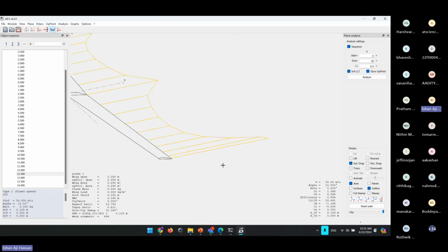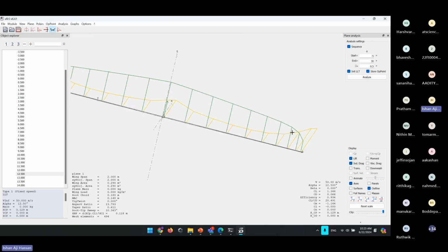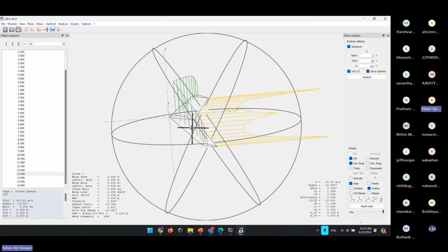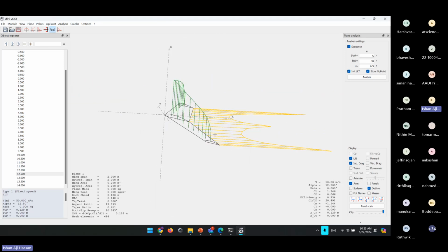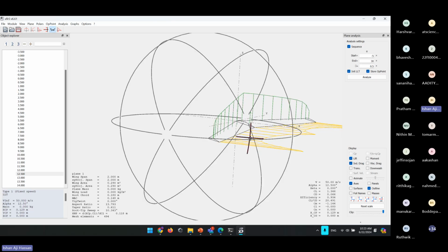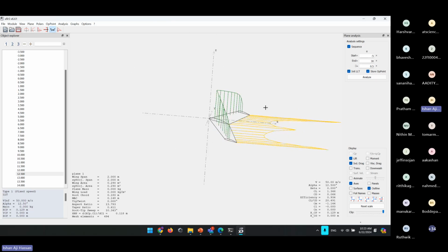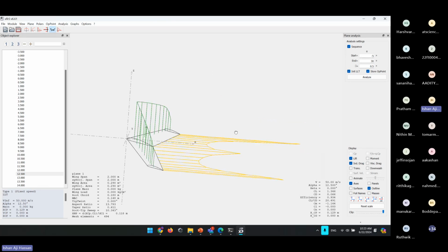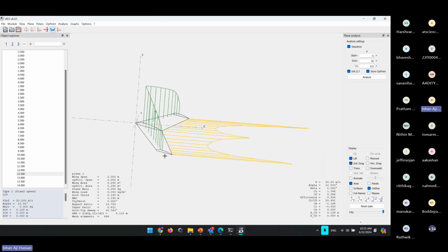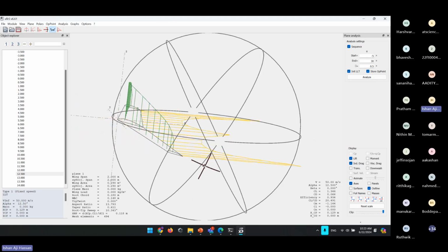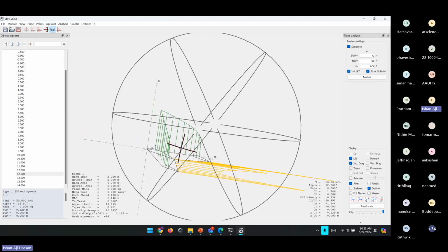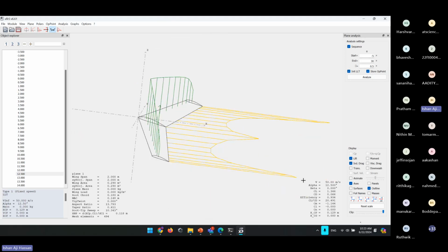And reducing the efficiency means that the lift component is basically angled backwards. So what happens is that this same aerodynamic force is acting almost entirely here, but then that aerodynamic force is angled a bit towards the back due to the wingtip vortex. And that means that the particular component of that angled backward lift is getting resolved towards the drag direction. And only a little bit of that is getting resolved to the lift direction. That is why this lift arrow is smaller. So that net aerodynamic force that is resolved in the drag direction due to this shifted lift is called induced drag.